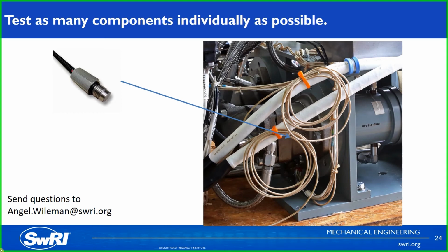And so one good example of this is for the hydraulic motors we were talking about earlier. They came with magnetic pickup sensors to measure RPM. Again, we threw this right in the system. It came from the manufacturer. We thought it should work pretty easily. As we started going through the commissioning, we felt like we were spinning faster than what this was picking up.